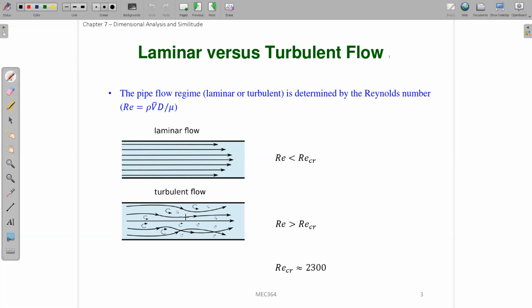The second thing is that for the turbulent flow, the quantities inside, no matter whether it is the density, the velocity, or the pressure, have statistical properties. They have some random behaviors. If you use your experimental equipment to measure the pressure field or the velocity field, at different times you may measure different values.